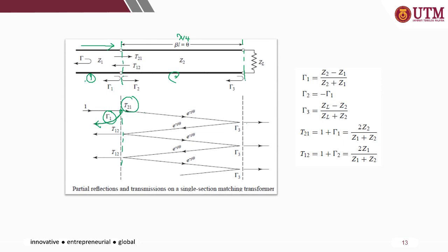All right, the signal travels along the lambda/4 element, and then there's another intersection. So there's another reflection at this intersection, given by reflection coefficient 3. This is the third point. Then some of it will be transmitted from 2 to 3. This is from 1 to 2.